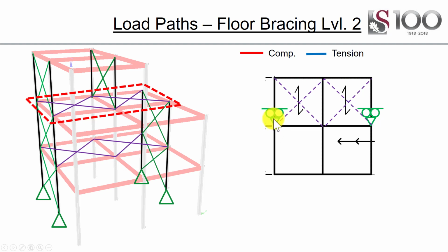As long as I'm consistent, if I put it at the front node, then when I do the vertical brace bay, I put it at the front node. Then you're less likely to double account for loads in the members here and here. So now there are my supports from my vertical bracing. I have my R1 load applied at the same node as where I transferred it from the last model, and then my 10 kilonewton load applied here. So now I've added my second lateral load, and then compression, and then tension. That is then the load path, and everything else is a zero force member.